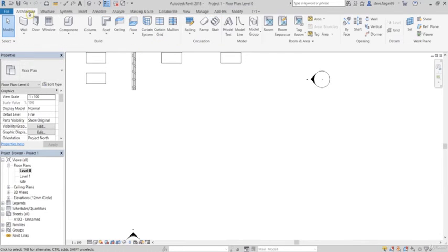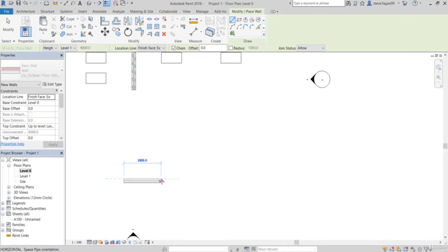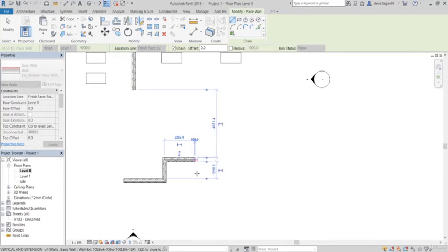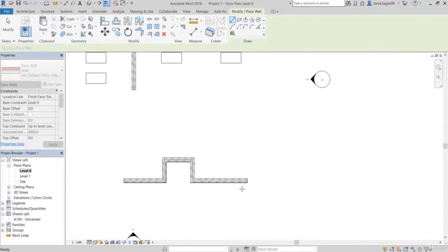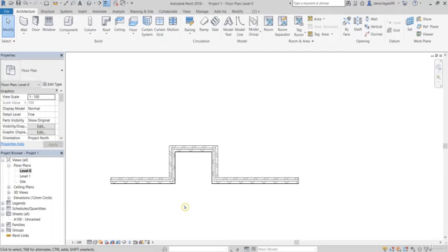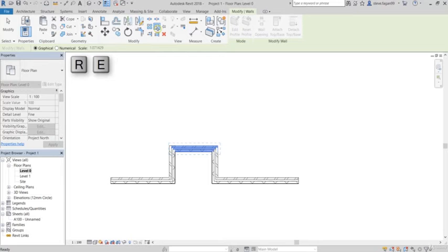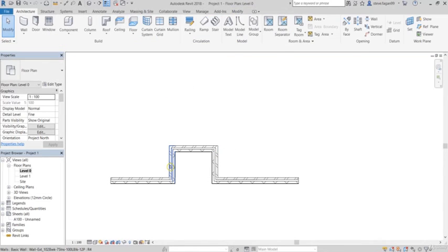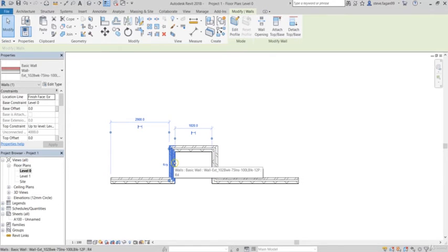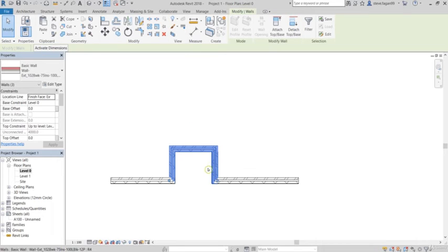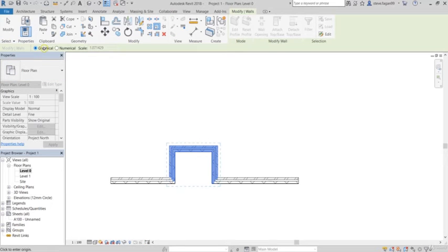So next, for the scale, what I'm going to do is just quickly draw a wall. And we have two different types of scale. When I select my element, selecting scale, we have graphical and numerical. First what I'm going to show you is the graphical scale. I'm going to first select all three of the walls. I do this by clicking on one wall, holding down Control and selecting all three. Then I'll select scale, remain graphical.